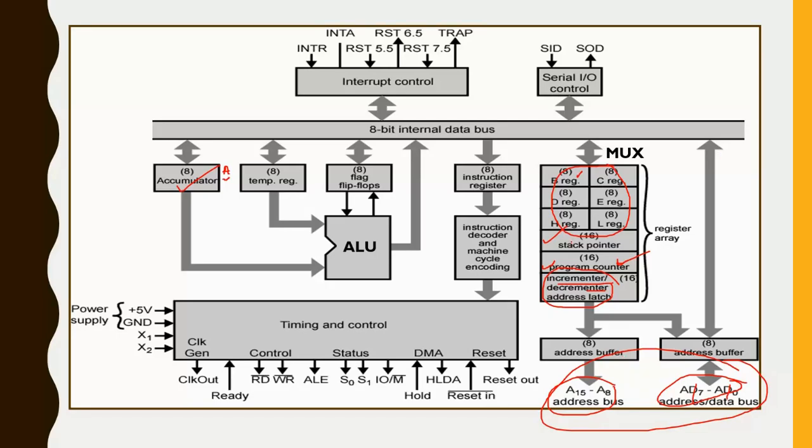It just means that we have 16 pins, in which those 16 pins represent the address bus and 8 pins out of those 16 pins represent the data bus, right? Then, when the address was sent to the memory, the read pin gets active. This means that we are reading from the memory, and then the data is sent through the data bus. So we came here now, right? The instruction which is sent by the memory is stored in the instruction register.